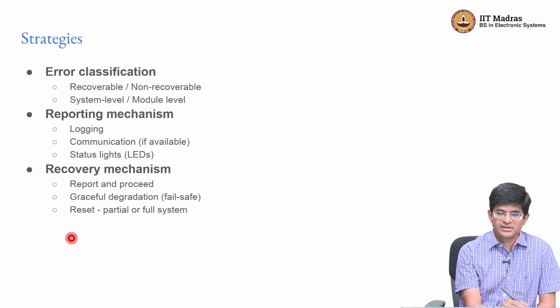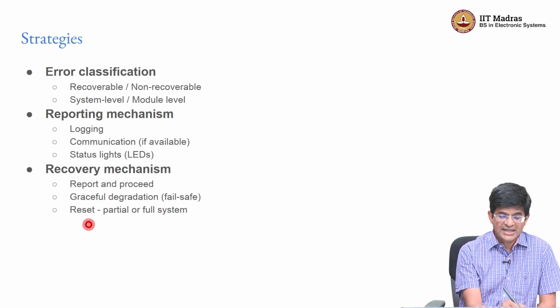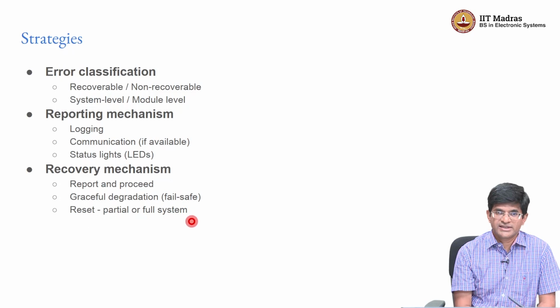And of course, in a lot of cases, it turns out that the recovery mechanism finally involves some kind of a system level reset, either a partial reset of only the affected parts or a complete shutdown and restart of the entire module. In many embedded systems, as far as possible, you do not want to have full system resets, but there can be scenarios where you can't escape from it, and that's the only option that you have.